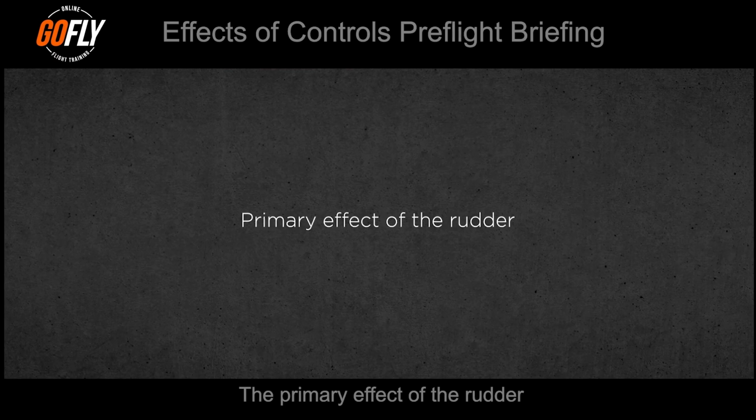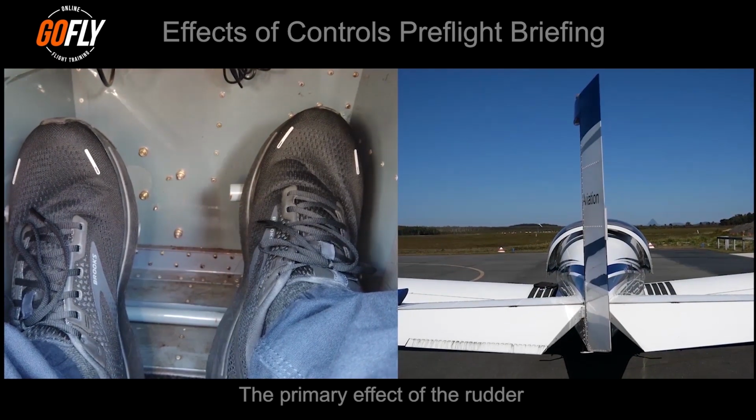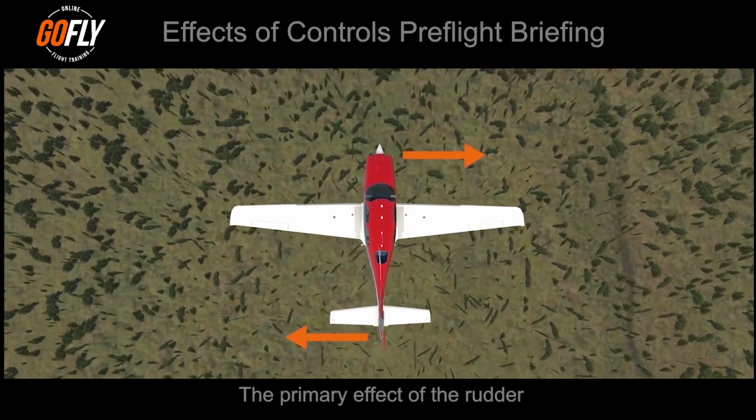I will now demonstrate the primary effect of the rudder. When we apply pressure on the right rudder pedal, the rudder will deflect to the right and create a force to the left, and the aircraft will yaw to the right.